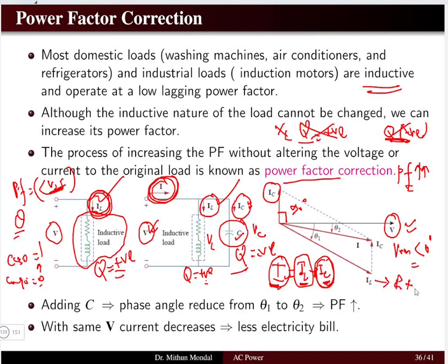One is the resistance and it also has the reactance, R plus jXL. Now this current IL will not be entirely at minus 90 degrees. This is due to the presence of this resistance. It will be at an angle of theta 1. So theta 1 is the angle which the supply voltage V is making with this current IL.